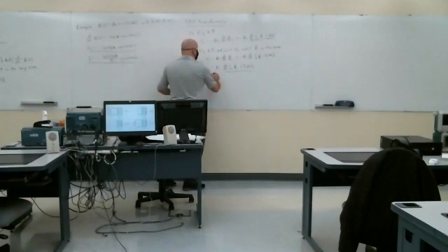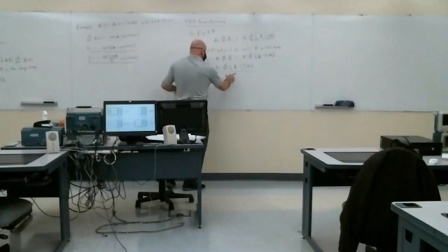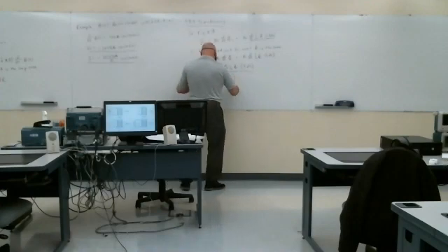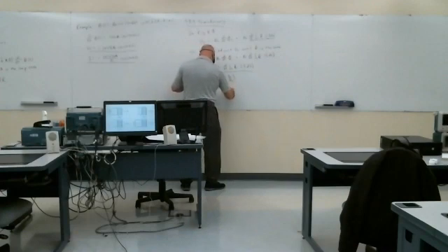So I can solve for this time derivative of this integral from this first equation, and it's going to be minus V2 over N2. If I make that substitution, that leads to V1 is minus N1 over N2 V2 as the relationship.